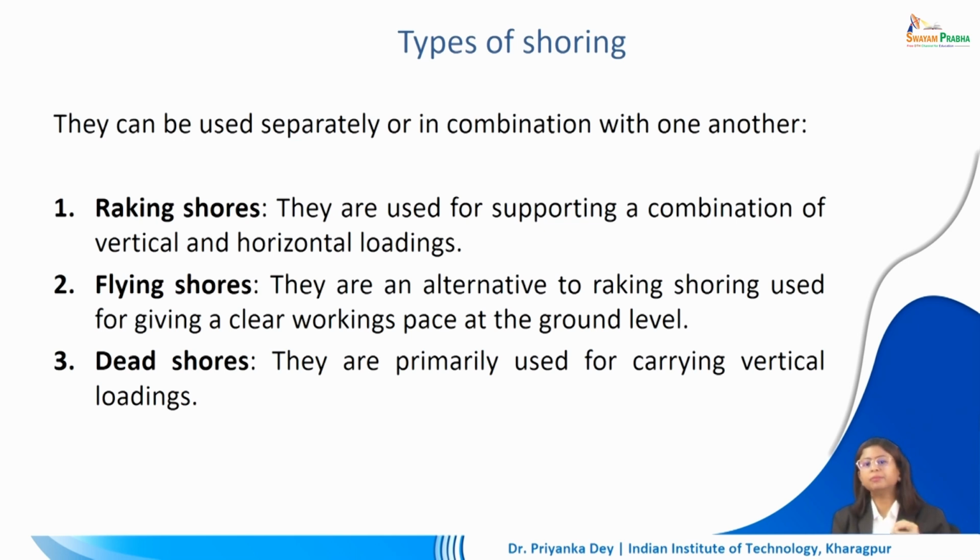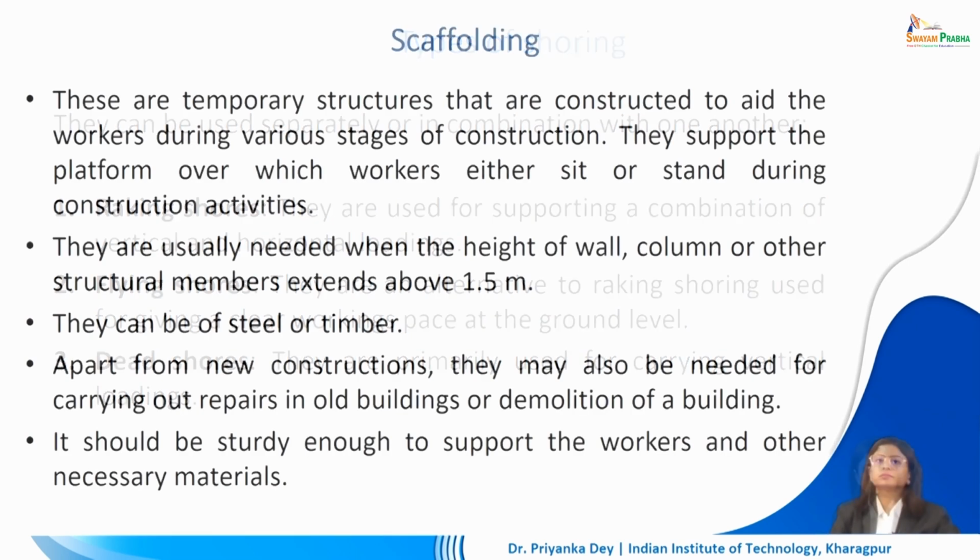Now, dead shores are mainly done to provide vertical support if you are creating an opening in an existing wall. So, if you want to support the upper portion of the wall, we can have 2 vertical members inside and outside that room to provide support while we create an opening within this wall.